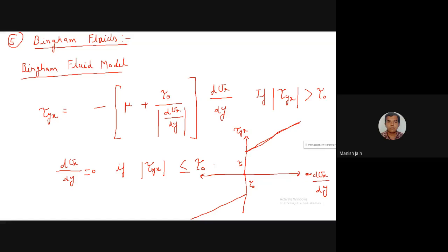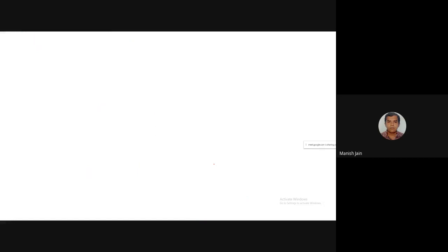So there are a number of types of Bingham fluids. Even glass is also a Bingham fluid. But the force required to make glass flow is very high. So basically all amorphous materials in the solid phase are Bingham fluids. Like rubber, pastes, jams, jellies, these all are Bingham fluids, or different types of slurries, or charcoal, that is also an example of a Bingham fluid. At lower shear stress or force, it shows the behavior of a solid material, but when you increase the force, it starts to flow.